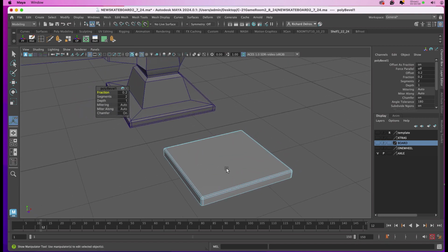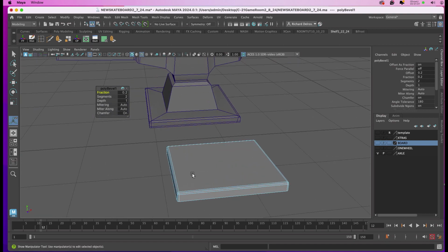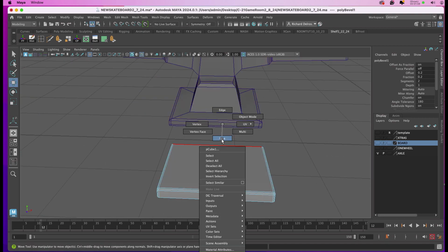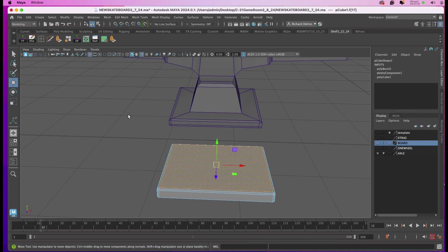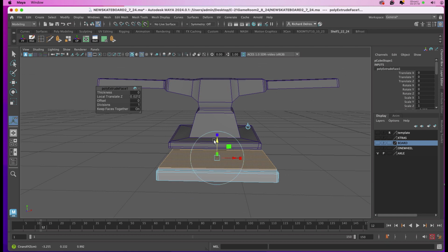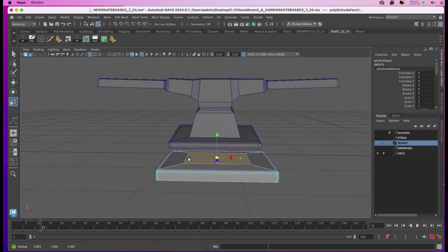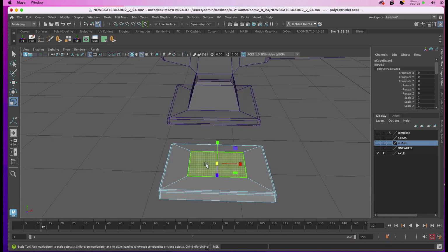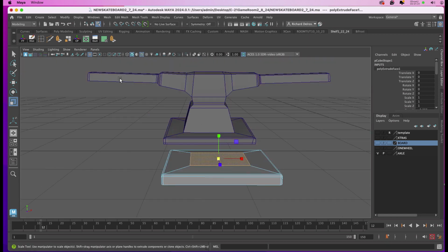And now we'll begin to extrude the other geometry we want here. I'll right click and choose face. I'll select the face in the middle. I'll click on my extrude tool, and I'm going to hit my scale tool, and I'll just pull that in to establish the size of the base that we see here. Once I've done that, I'll either click on the extrude tool or hit G to repeat it.